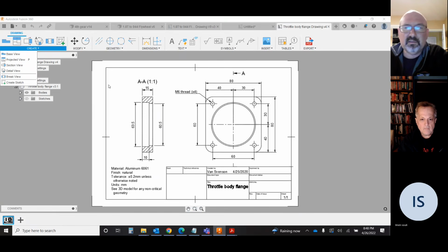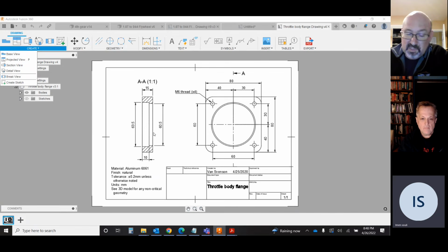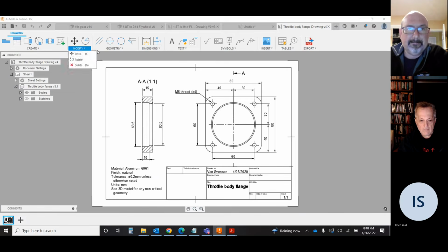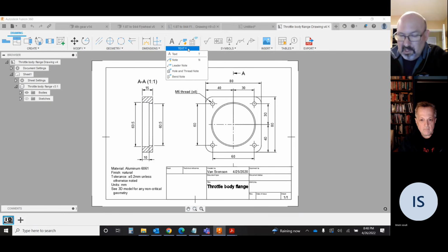But in my mind, the goal of a good 2D drawing is to keep it simple enough so that the part can be understood, and that any critical dimensions that you might want inspected, or that might be ambiguous or unclear to the manufacturer, get notes to help make it clearer.